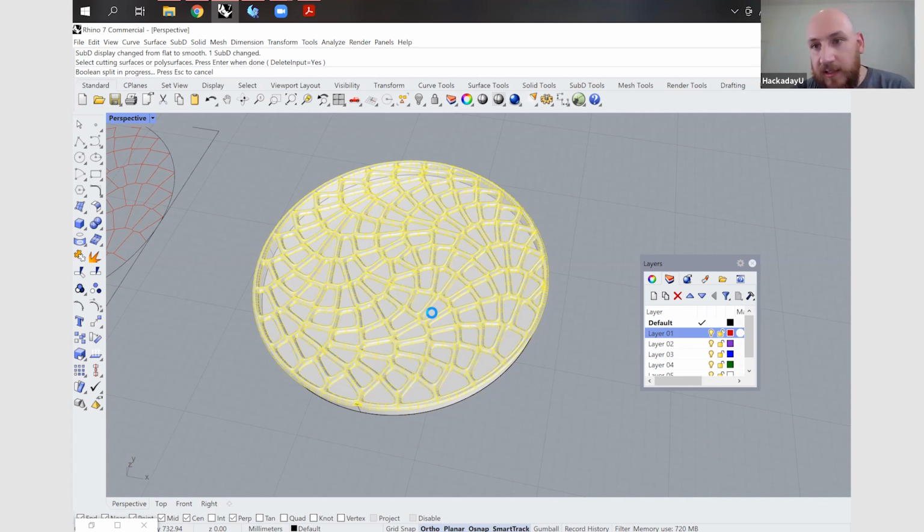But from controlling a CNC machine perspective, we actually just need these curves and then to assign a ball nose router bit, which is the one I showed you at the end of the slideshow, to those curves, and then it will move on the line, profile cut these curves, and this would be the end result. So for CNC machining, we actually just need the curves. And it's going to take a bit to build in.